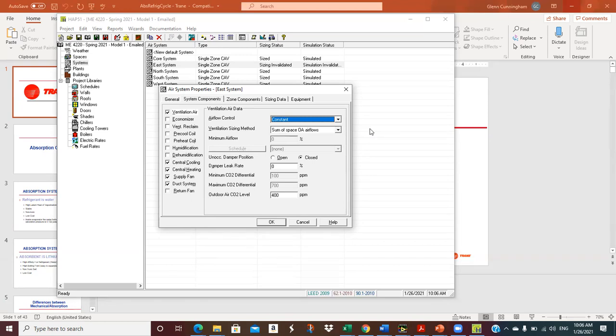If the whole building is not occupied, you're not required to ventilate. But a building like this potentially has people here 24 hours a day, so if you were controlling this building, you'd probably want to keep some ventilation going. Okay, so we'll just look at these, and we'll go back and we can add that economizer.